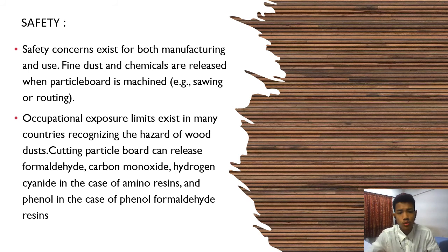Okay, the last one is safety. Safety concerns exist for both manufacturing and use. Fine dust and chemicals are released when particle board is machined. And number two, occupational exposure limits exist in many countries, recognizing the hazard of wood dust.